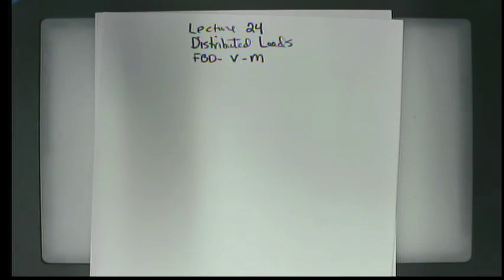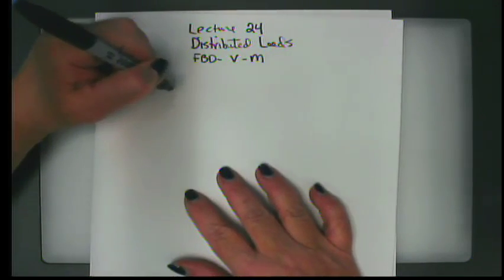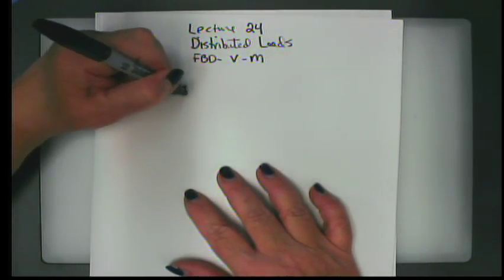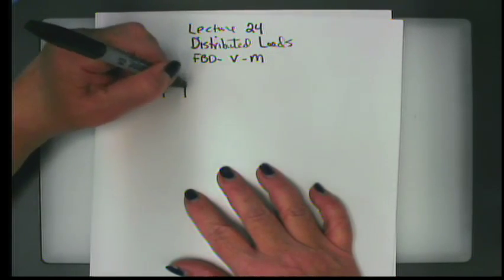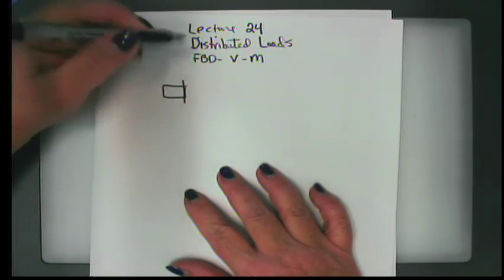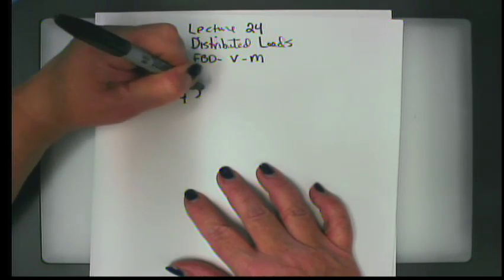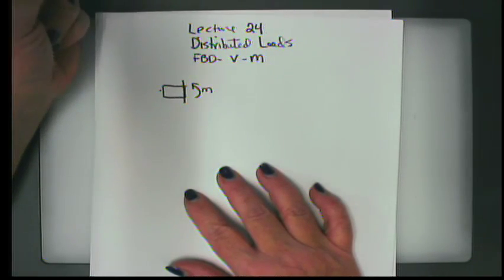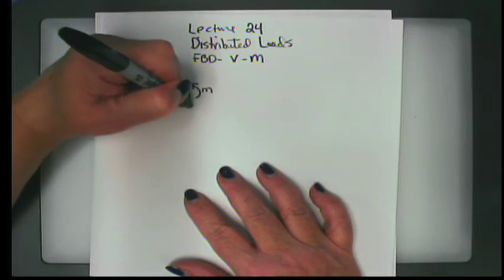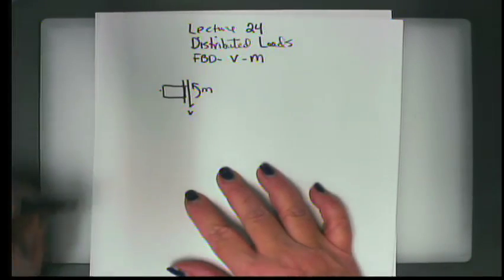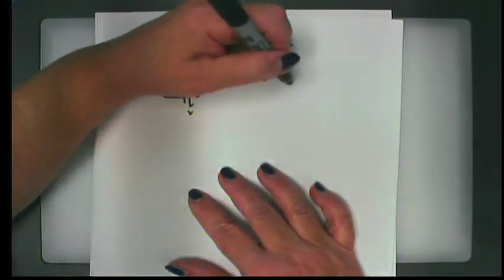So the first thing I'm going to do is go back and refresh a little bit on the sign convention. And what we have said is that we always have to do a cut section or a cutaway. And if we start at the left and cut on the right, a moment like this, a counterclockwise moment, is positive, and a shear, responsive shear down, is negative.